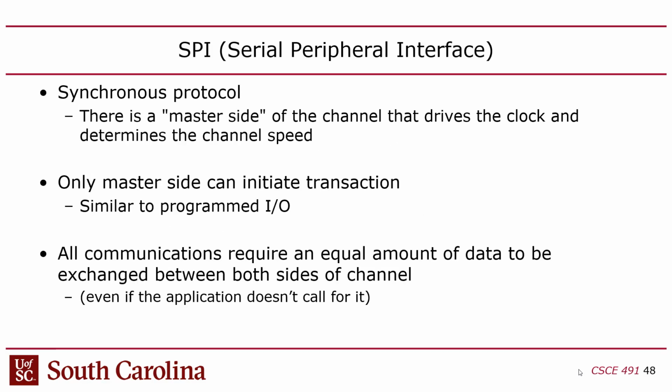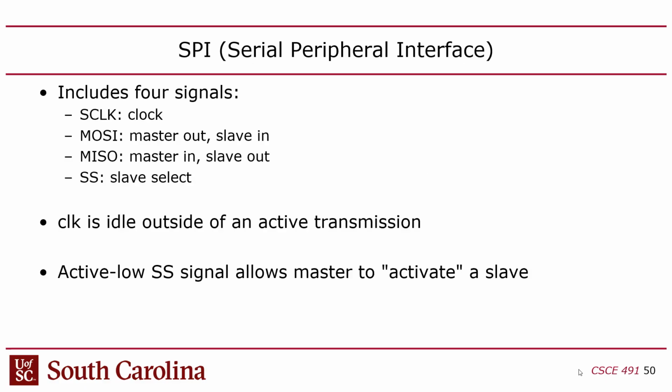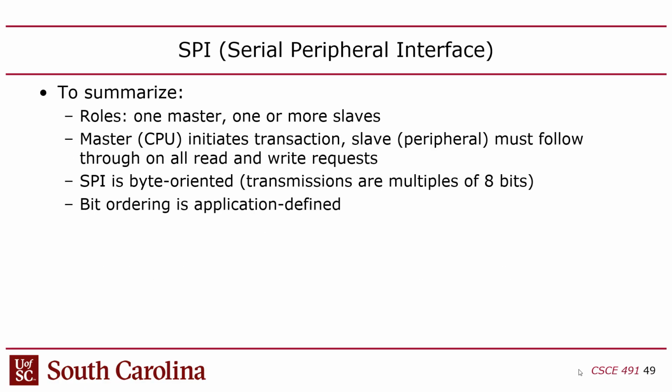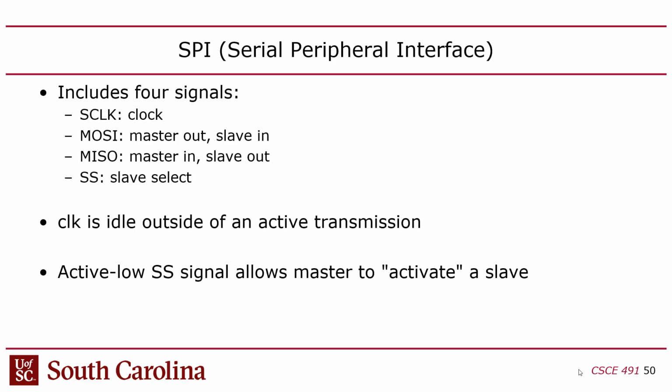Another thing too is, there are a few other ways that you can distinguish these protocols. Some protocols can only have one sender, one initiator. That's called a single master type bus. Other buses, when I say bus, I mean communication protocols, can have multi-master, where you can have more than one entity that's allowed to speak. Do I have any other distinction here? Yeah, so that's the other distinction. So we have synchronous and asynchronous, and single master, multi-master.